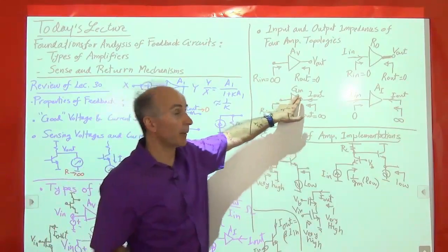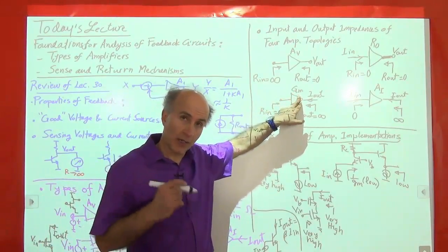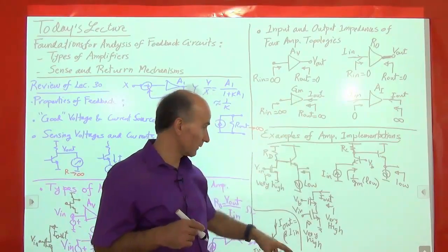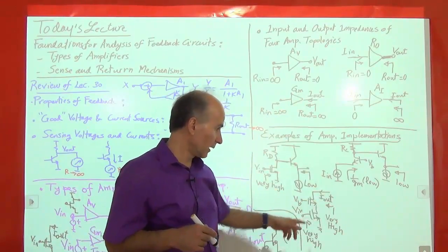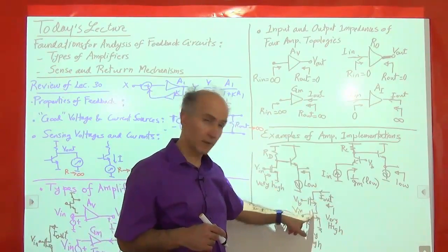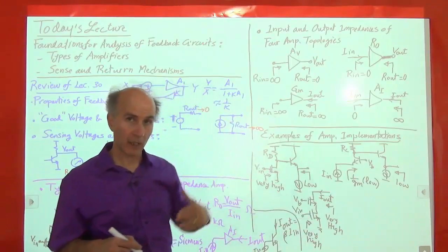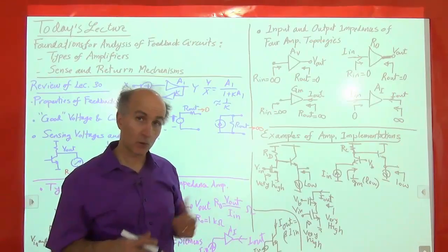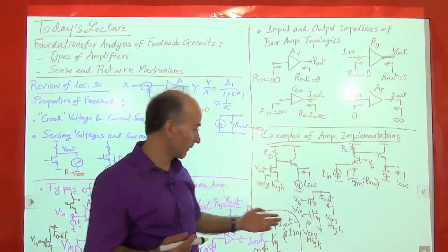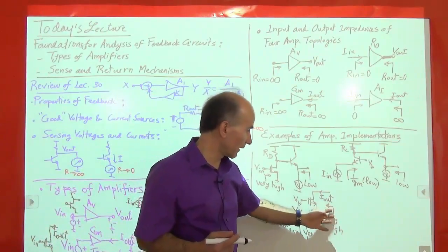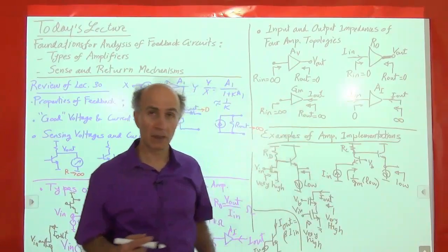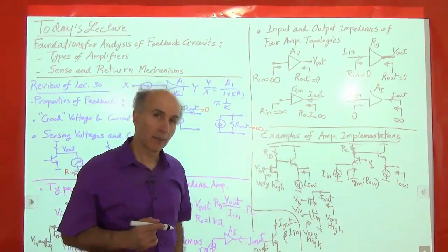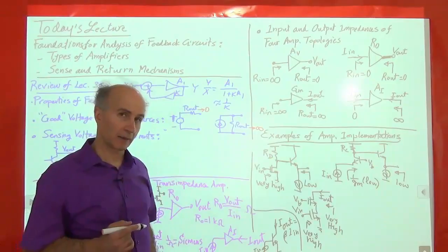We have some transconductance. The transconductance of the circuit, which is defined as I out over V in, is approximately that of this device, if you remember from our studies of cascode structures before. So we have gain, and then we have a high input impedance, we have a high output impedance, so that's a nice implementation of a transconductance amplifier.